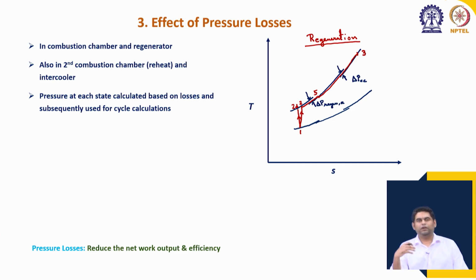So, why is there a pressure loss in the combustion process? So, in combustion we need to sustain the flame, which means that if the flow is very fast through the combustion chamber and it is very streamlined, there won't be any locations where the flame can be sustained, okay. The flame will blow out of the combustion chamber.